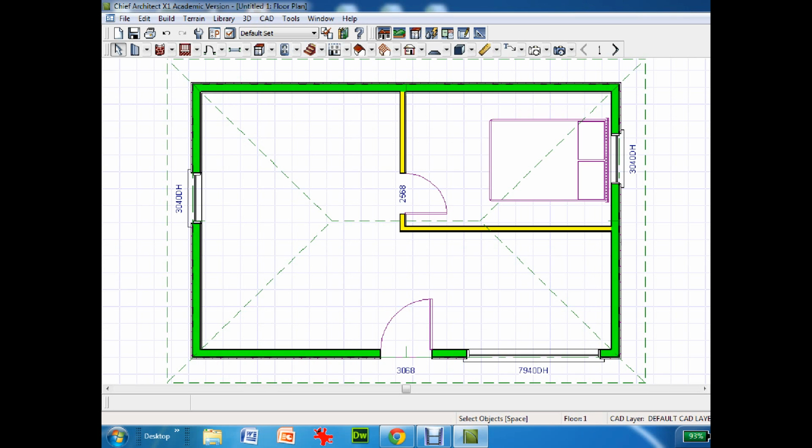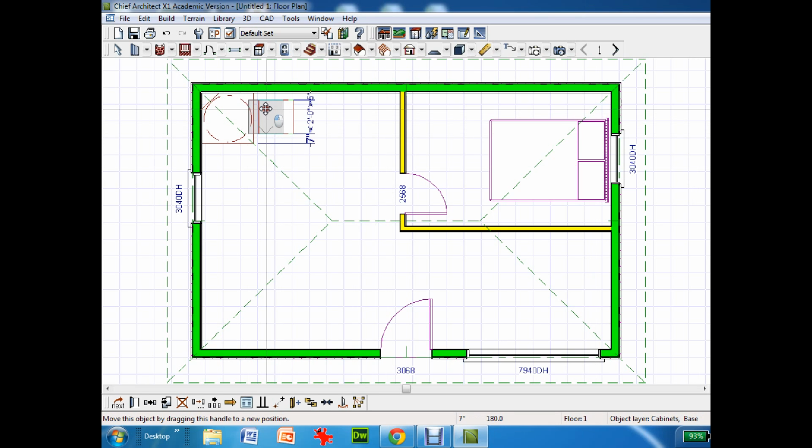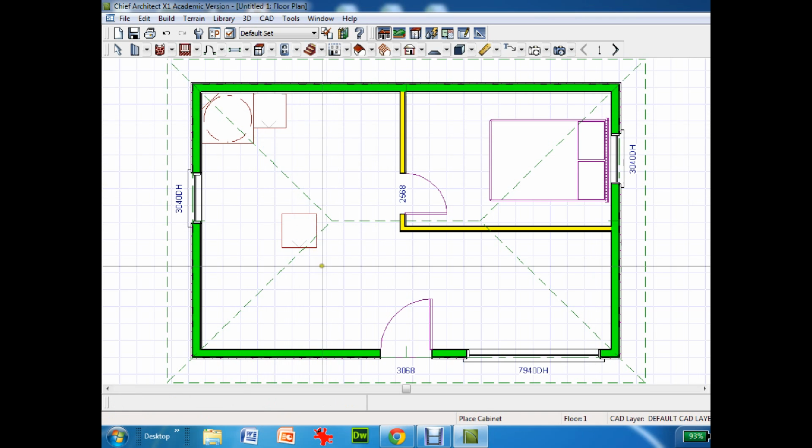So kitchen, the basic thing is cabinet modules is what you want. So go base cabinets, because those are at the bottom, and wall cabinets are up top. So base cabinets, and I can just do, well, geez, I need a corner one, and I'll click on that, right? Just click and hold that, and put it in place. And then I want to take a double door one, and I'll put a small one. I'll put it here, and I can click on it and just go in like that. Okay, and then I can probably just go over a bit. There we go. And now when I view it again, I'll put one more in.